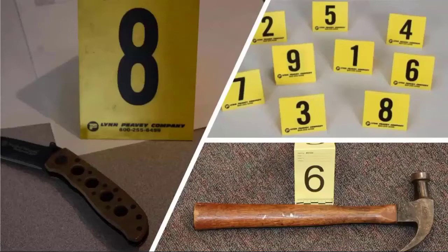Identify your evidence before you scan. Sometimes we get in that rush to preserve the scene, and we forget to do that, or we'll scan first. And I've been asked, well, what happens if I identified my evidence and I scan, and then I find another piece of evidence? Well, my recommendation there would be to take a close-up photograph and add that photograph as an annotation into the software at a later date.